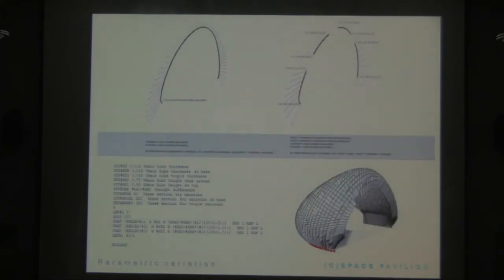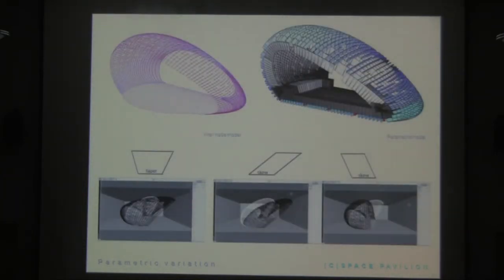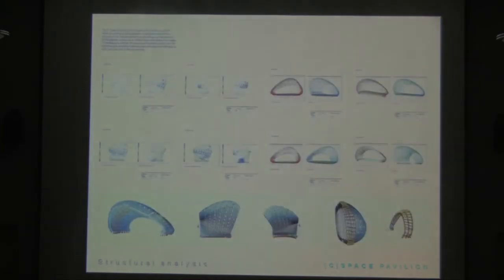And so you can see here it starts to do what basically Gothic arches or Gothic vaults do. They widen towards the nodes. And as you can see there, it's starting to get really, really thick and far, far deeper than what we were interested in, as you saw from our initial diagrams. So we're beginning to work with this geometry, rework it, and finally we got it down to a reasonable depth. We did have to include this little dark secret, which was the 3 steel continuous beams which we painted gray and pretended were concrete and didn't tell anyone about.